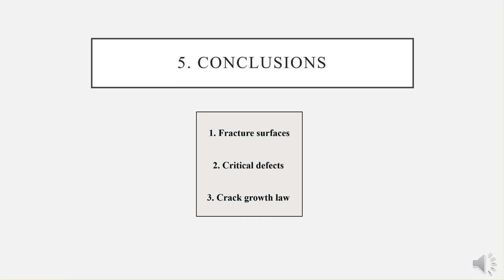To conclude, in the present work, we analyzed experimentally several fracture surfaces of a titanium alloy fabricated via selective laser melting, and a common pattern of 4 different regions was observed in these fracture surfaces. Also, the critical defect initiating the crack evolution was localized in the fracture surface and quantified making use of both scanning electron and confocal microscopy, so that its shape and character, that is, blunt or crack-like, were determined. In order to attempt for a numerical simulation of fatigue crack growth, we developed a crack growth law considering crack closure evolution, which eventually led to satisfactory simulations.